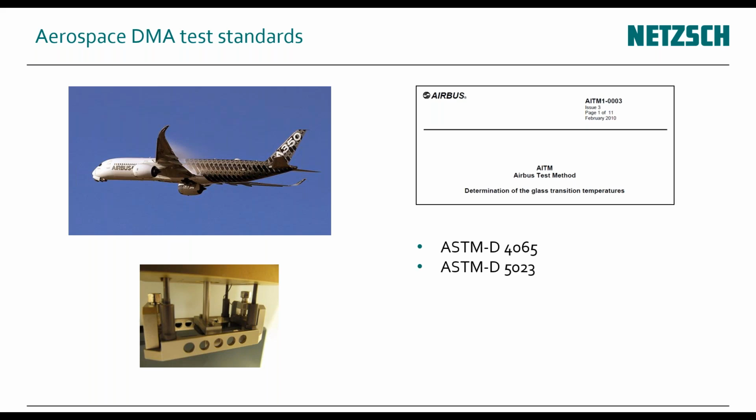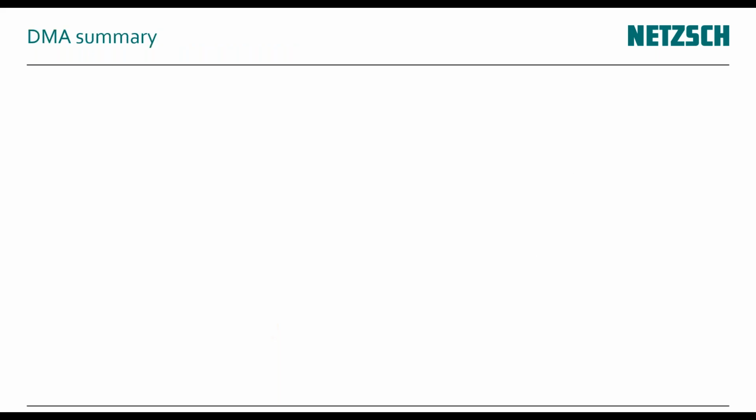There are several standards applied. This is the referring ASTM standard, D4065. There's another one, 5023. Most widely used, I think, especially in the US, is ASTM D7028. But this again refers to the same kind of measurement using dynamic mechanical analysis. There's another one that is not so widely used, as I mentioned, the Airbus AITM 1-0003.